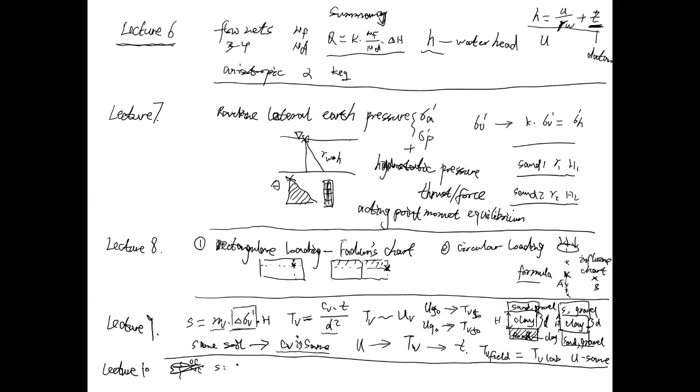So maybe 1 is the OC formula, 2 is the NC formula, and 3 is the OC plus NC formula. That's the utmost important part of this lecture. You have to work out the initial effective stress, the final effective stress, and also the pre-consolidation stress, the 3 values first, and then you draw the 2 line segments like what I did. Always this is OC and this is NC stage, and this will be the position of sigma P prime.